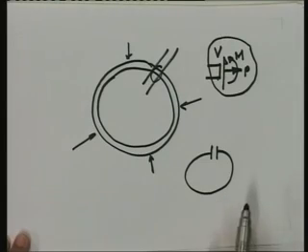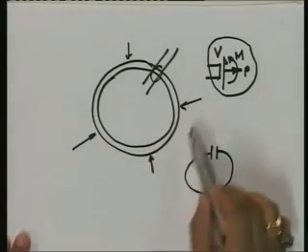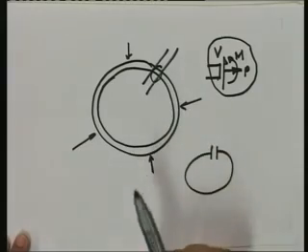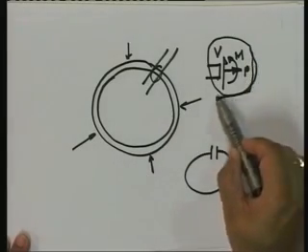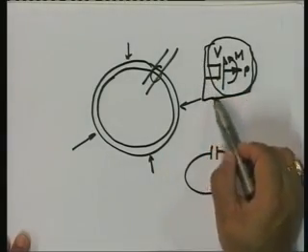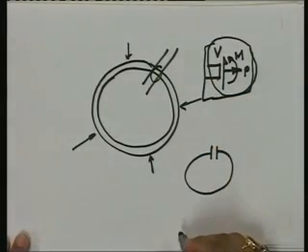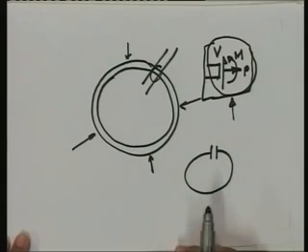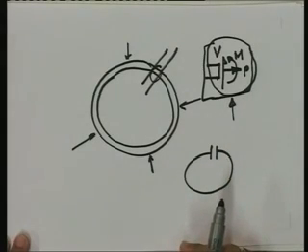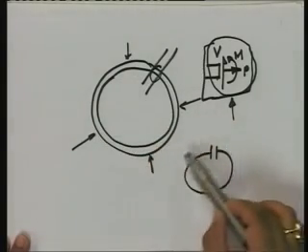And note this, that in this particular problem, when I make this cut and I generate these three, can I find them out? Think about it. I can't. These three are unknowns, which I cannot find using any equilibrium equation.